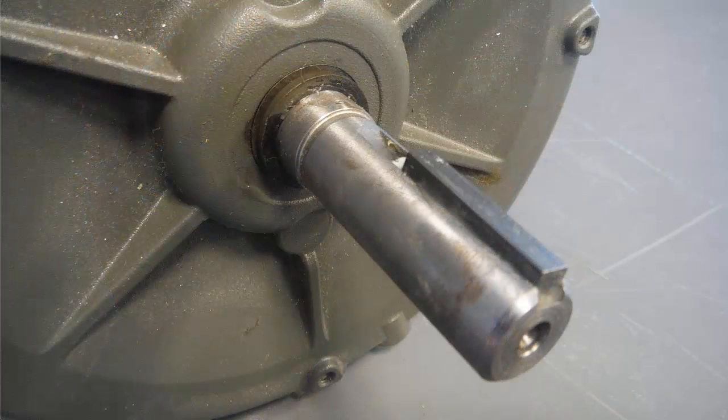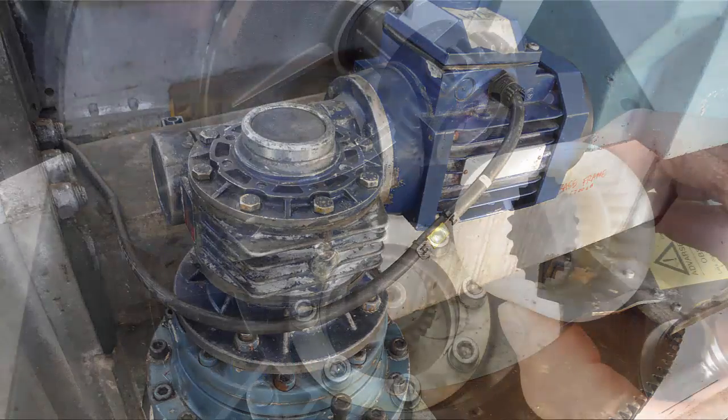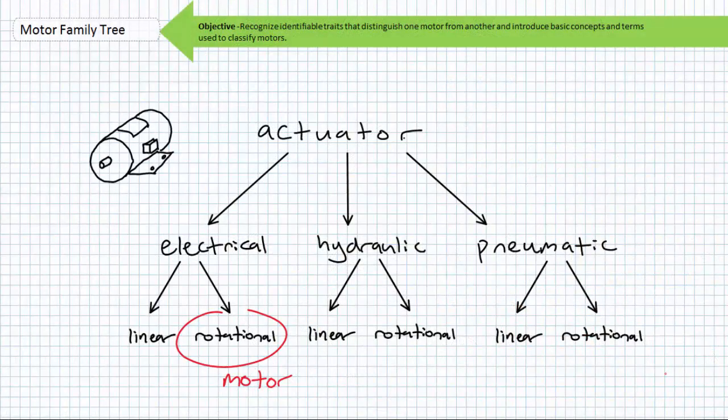The shaft is the spinning thing that sticks out of the body, and the shaft is normally attached to something that needs to be spun. Most of the time there's a key or keyway on the shaft to directly couple the shaft to the load, a coupling, or perhaps a gear or gear set to increase torque and decrease speed, or the other way around. A coupling compensates for misalignment of the shaft with a load and enables a technician to take it apart. The gearbox and coupling aren't actually part of the motor, but they're essential for the motor to do its job.